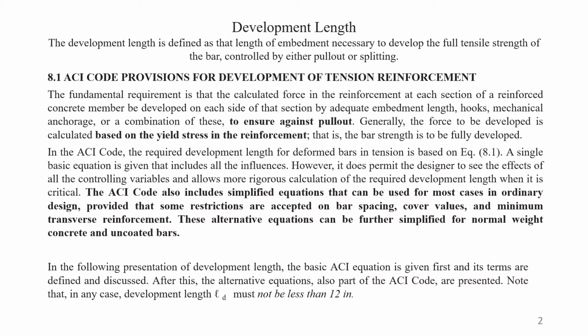As we have discussed in an earlier class, these two materials have properties that are very significant for use in combination, so that the concrete will take the compressive strength and steel will take the tensile strength, or compressive strength wherever necessary.